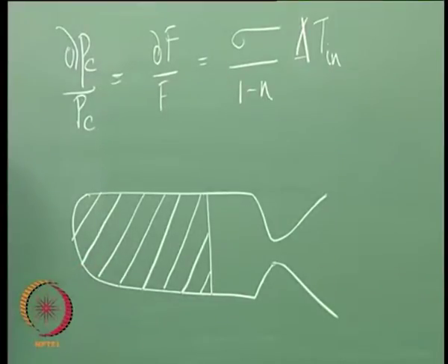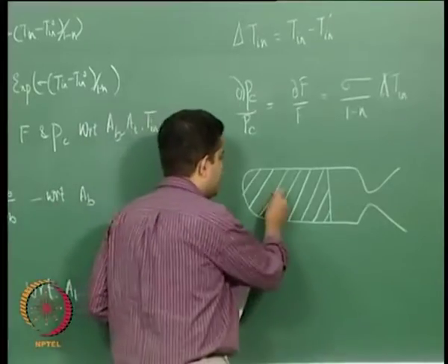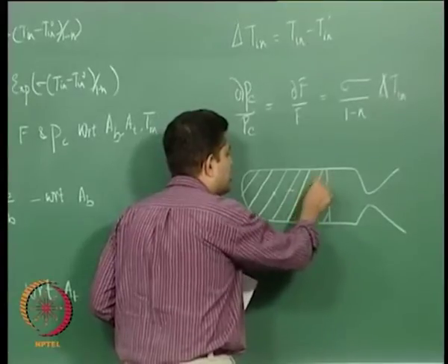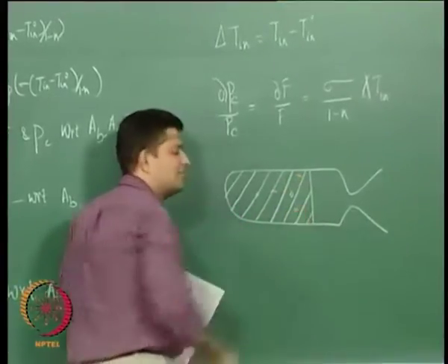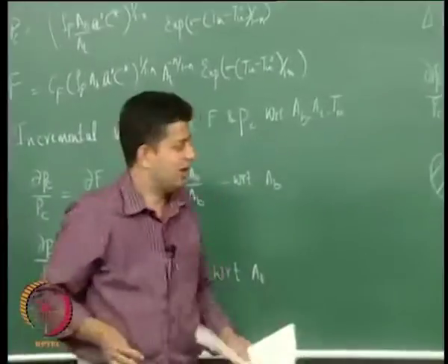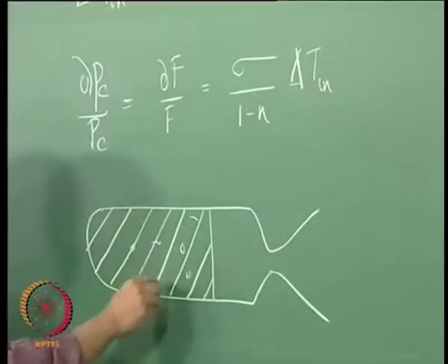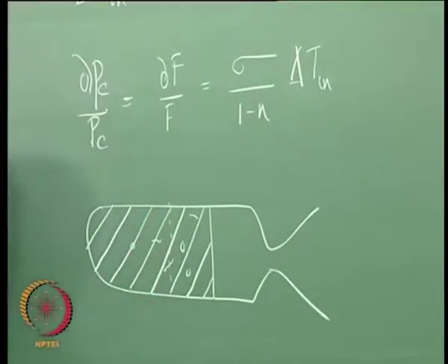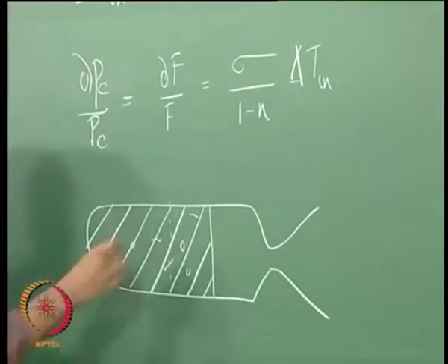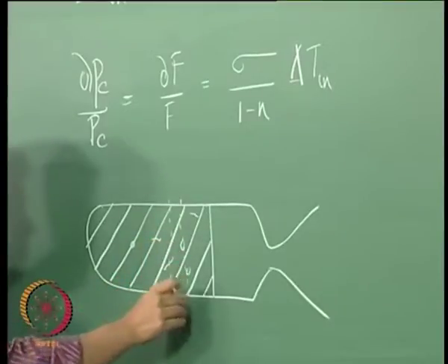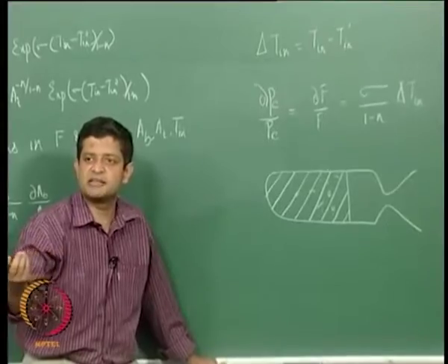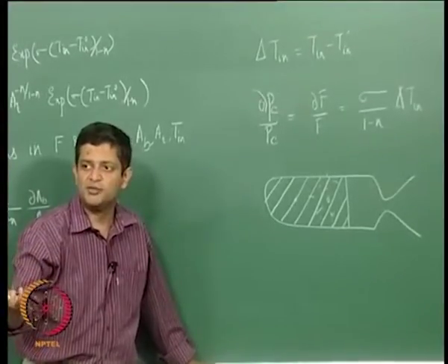Okay. Either process you will have some kind of imperfections, that is you will have somewhere cracks, blowholes, right. So now if the flame comes to this position, right, let us say the position is somewhere here, or if it is somewhere here, it sees an additional surface area, right. Suddenly an additional surface area is exposed to the flame.